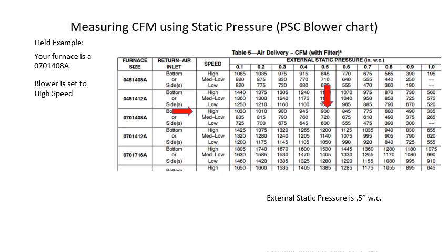If you have different kinds of blowers, you just need to know how to use those charts. When you take your external static pressure, you compare that on the blower data, you can get pretty close on what your airflow is, and you can plug that airflow into your formula.